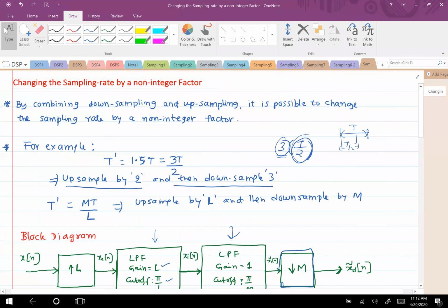So that's why now you try to interpret between these two directly, these two discrete time signals, and see that this should be the first one, the second one should be the downsampled version of the given discrete time signal. So if you want to do that, you simply need to keep the additional copies here. If you are downsampling by factor m, it is equivalent to placing in between m-1 copies. Am I clear?